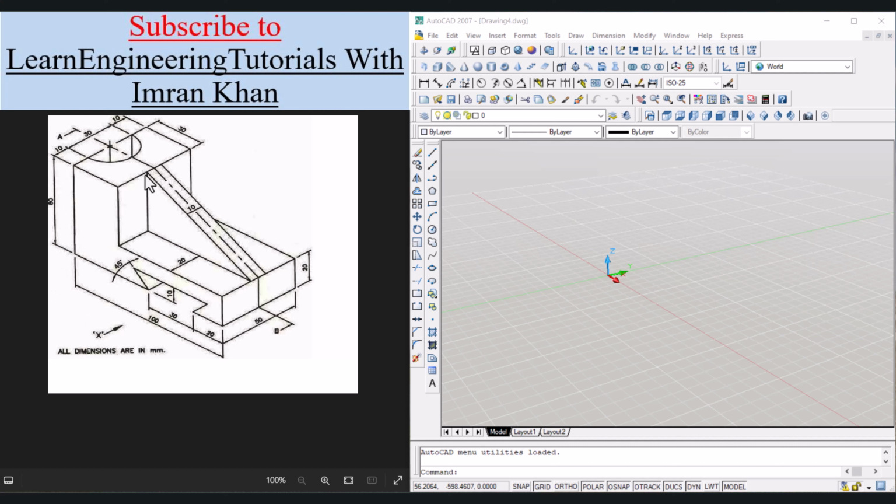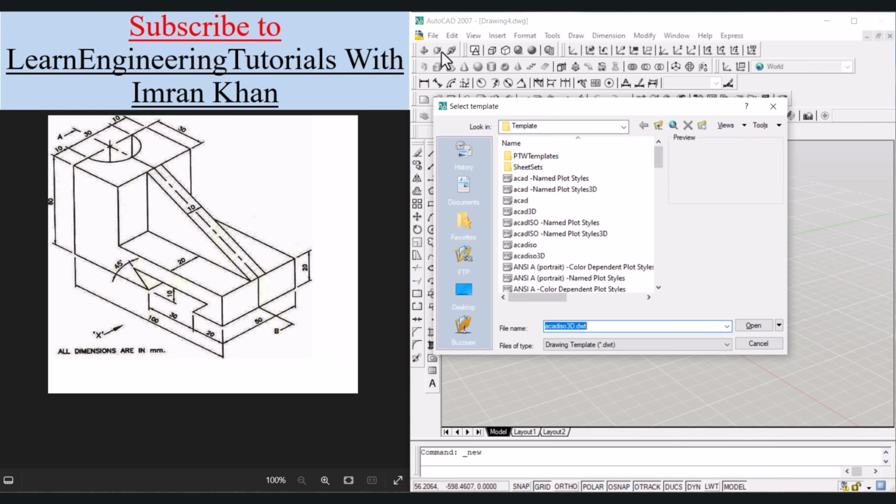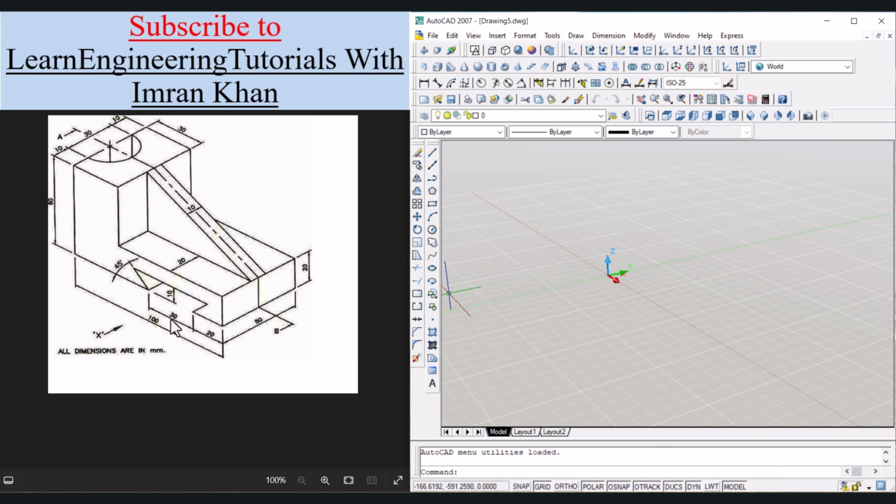So let us start drawing this object now. First we have to go to file, click on new. Now click on AutoCAD ISO 3D because the units are in mm, so we will open an ISO file. So this is the ISO 3D file.